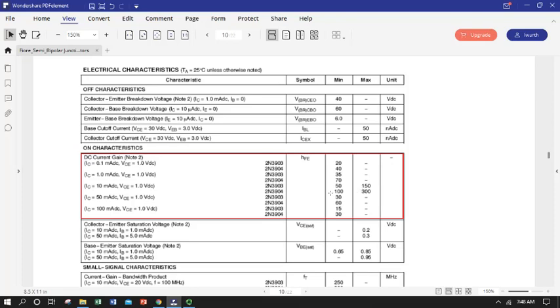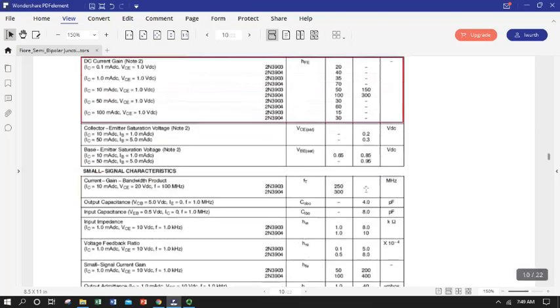That makes it hard to design a circuit that is reliant on the transistor gain. And because of that inherent variability in gain that is a product of the manufacture of the semiconductor device, that material science, we have a whole array of amplifier circuits that take advantage of these transistors that are designed to account for that variability in beta. They still make use of it, still give you that gain, but cancel out the variability somewhat so that we can still get the amplification we need without having our entire circuit output fluctuate with beta. We'll get into that in what we call common mode amplifiers. But just remember that the need for some of those designs started with this big old wide variation in beta.